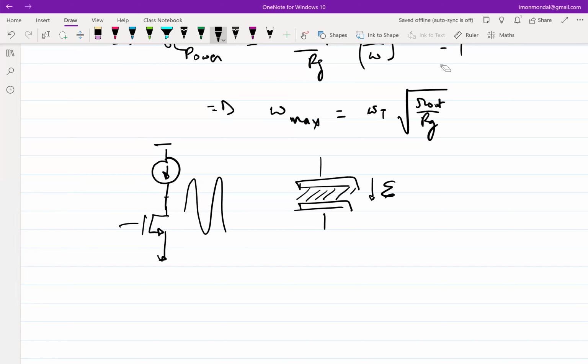So basically, if we know this, you have this capacitor here, CGD. Similarly, you have a capacitor from drain to body, CDB. Which essentially means that the dielectric associated with those two can start to break. Now, can you comment on which one will break first, CGD or CDB?